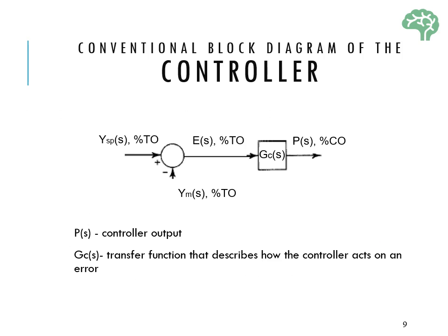Okay, the figure shows the conventional block diagram of the controller. So this is your controller, the feedback controller. As I mentioned earlier, this is the error that we want to reduce. The error is produced by the difference between the input measured by the sensor transmitter and the deviation from its set point. Alright, so this is the error.